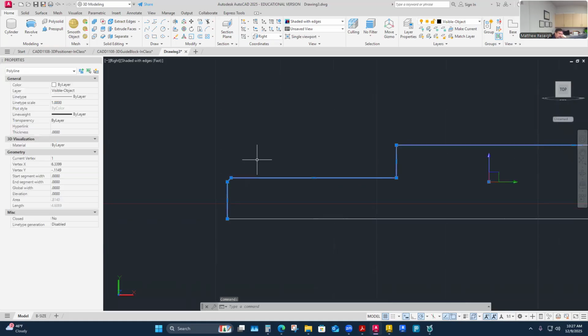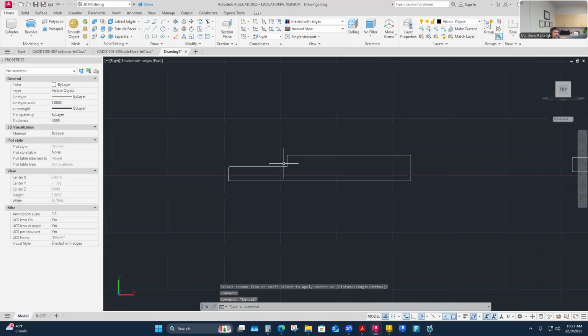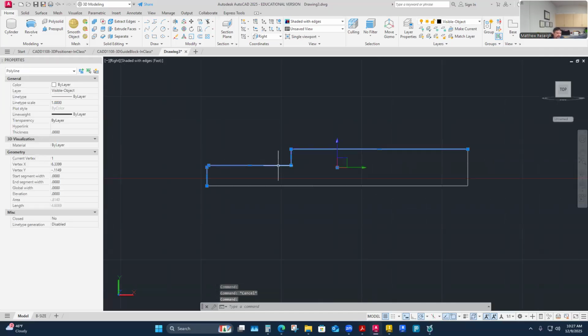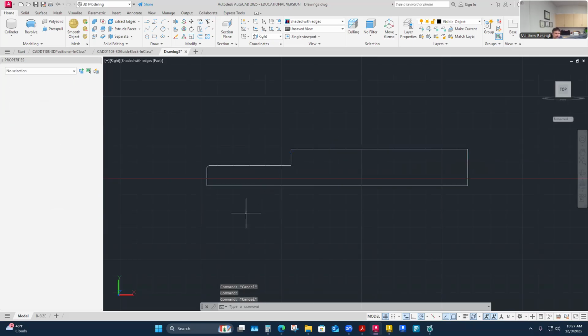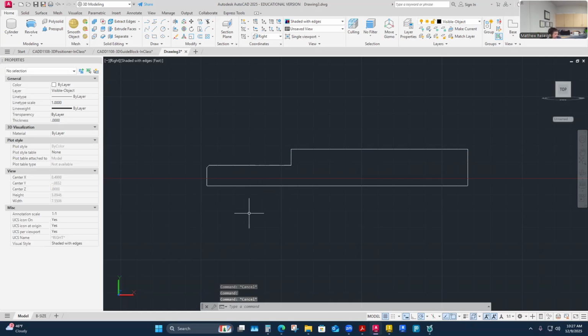And now, I don't know, this is a polyline. I've got segmented polylines here. I drew them as a polyline, so they are connected. But I'm going to join all these as one. And I think this is pretty critical. I think Abby drew this up yesterday and we experimented with it. It might be the difference between using polylines and lines. If you don't join lines, maybe it makes a surface rather than a solid. And I want this to become a revolve solid. So what I'm going to do is join these. I think it's just a good habit in this particular case to make a solid.